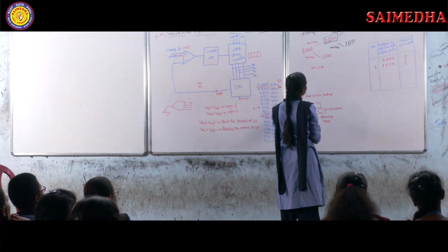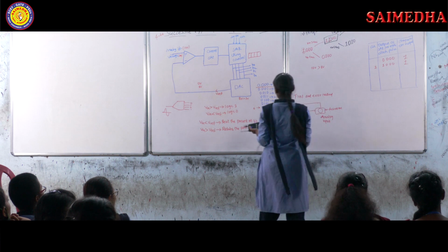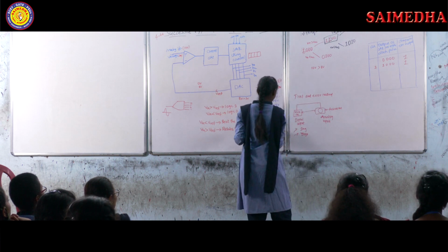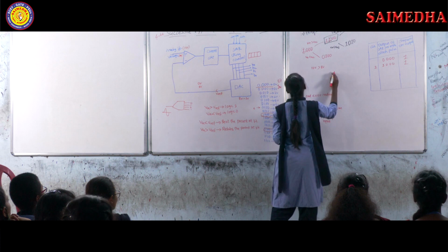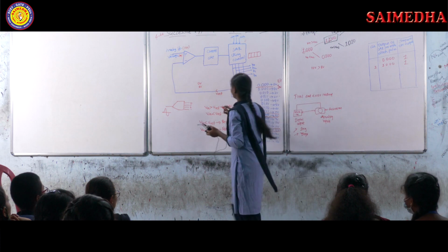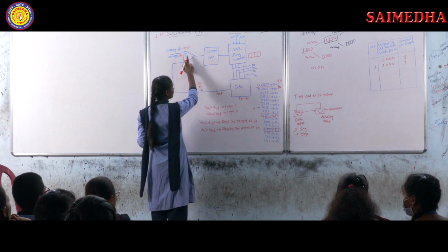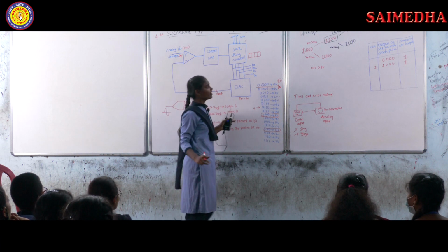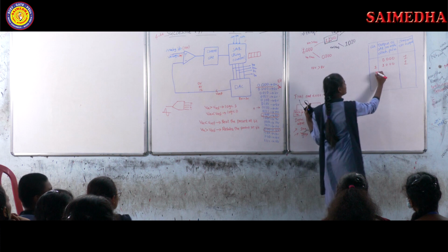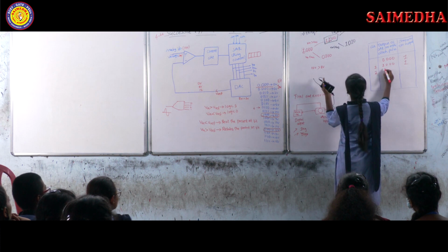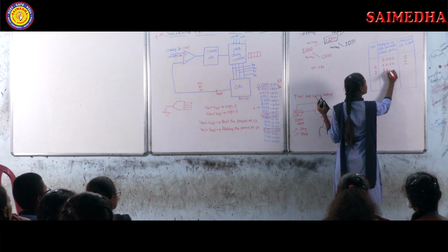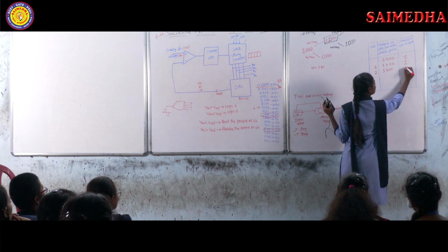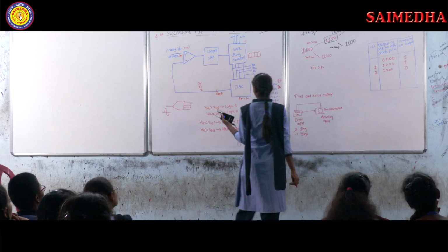And 1110, the corresponding voltage, is 12 volts. Here 10 volts is less than 12 volts, so Vin is less than V reference and we get logic 0. So for this clock pulse, the output goes back to 1100, because Vin is less than V reference.